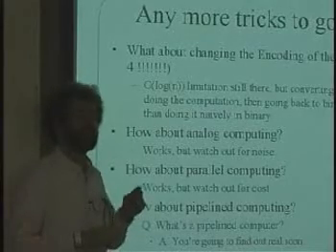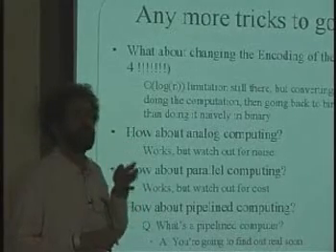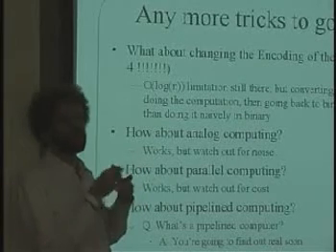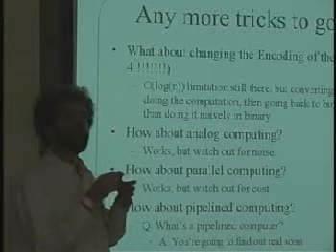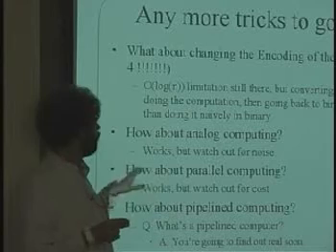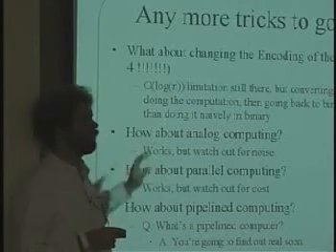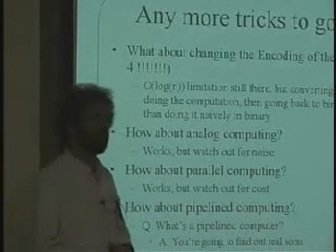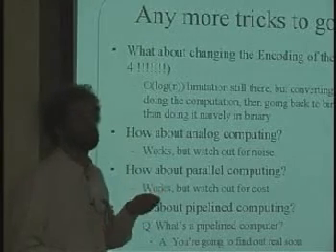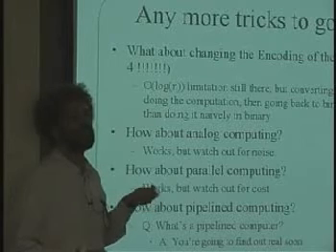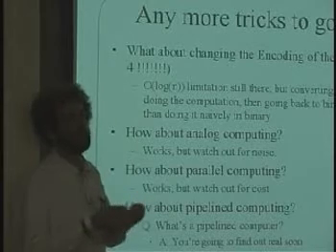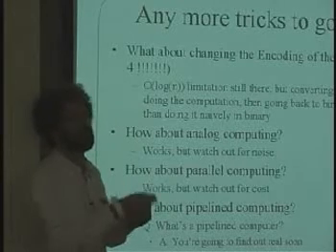It turns out that you could actually encode more possibilities in a voltage range. So you could, for instance, say 0 volts is a 0, 1 volt is a 1, 2 volts is a 2, and 3 volts is a 3. And every wire can now take 2 bits of data, being a number between 0 and 3. Okay? And you can do more and more of that to, in the limit, having what's called an analog computer. And of course, there you don't have any digital system at all, but you have just a voltage meaning what the number is. And to add 2 voltages to each other, you use an amplifier, what's called a summing amplifier or an op-amp. You sum the voltages and you get a sum out.